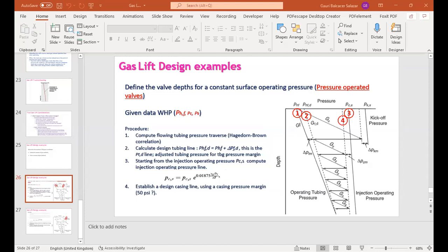So in this case, the inflow performance curve for the gas injection inside the tubing can be expressed by this equation. This is a function of the rate, the average pressure, reservoir pressure, maximum rate, and the gradient and the setting depth of the perforations and the valve. Again, this is the gradient we got from the API fluid.